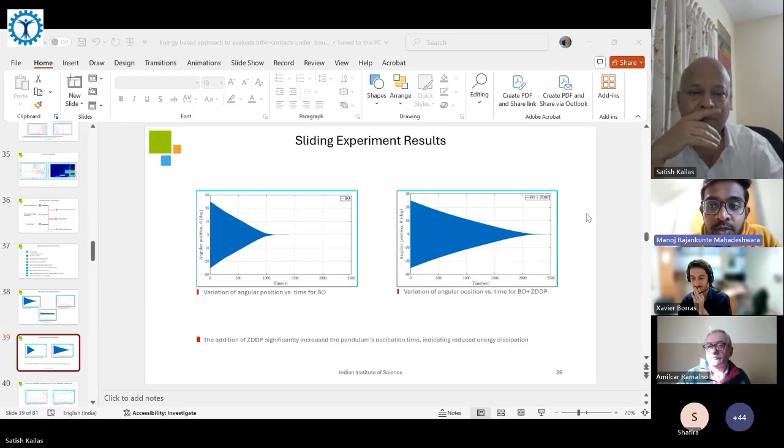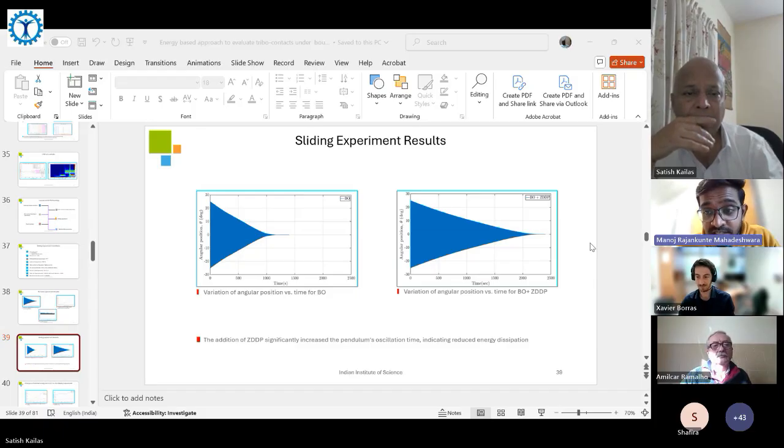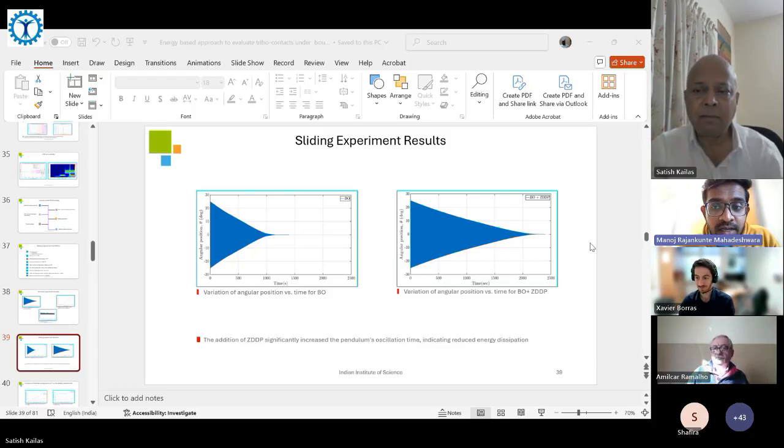The Stribeck curve demonstrates the transition between different lubrication regimes. Suppose you are designing a mechanical system that operates under varying speed, load, and lubricant viscosities. If you notice excessive wear, even at high speeds, where hydrodynamic lubrication is expected, what possible factors could be causing this unexpected behavior? And how would you troubleshoot and optimize the system for better performance?